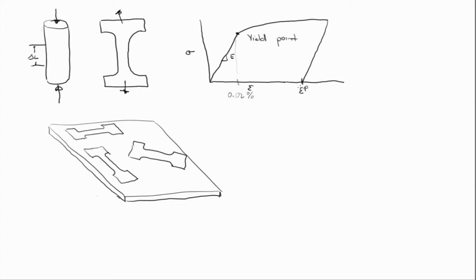And we all know this. I mean, anybody who's played with a paper clip, right? If you just pluck the end of a paper clip lightly, it always goes back to its original position. But eventually, if you pull it too far, then it doesn't go back, right? You've plastically deformed the paper clip. Right? And of course, the actual shape of what the curve looks like beyond the yield point is different for all materials.